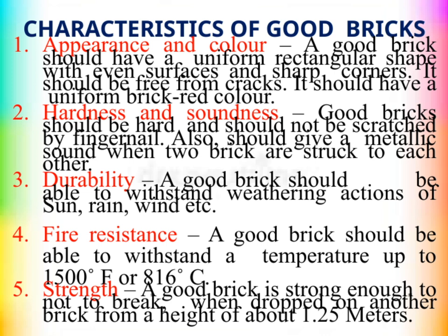Lastly, strength is vital. When you drop a brick from around 1.25 meters onto another brick, it shouldn't break. This kind of strength guarantees the brick can handle everyday stresses and loads without failure. All of these characteristics, appearance, hardness, durability, fire resistance, and strength, are what define a good brick and help ensure the durability and safety of the structures we build.